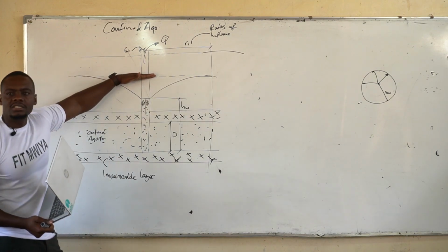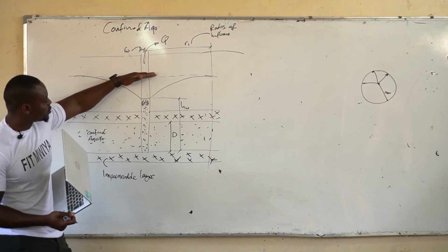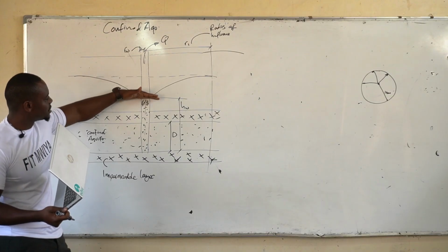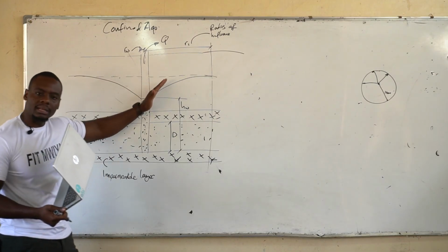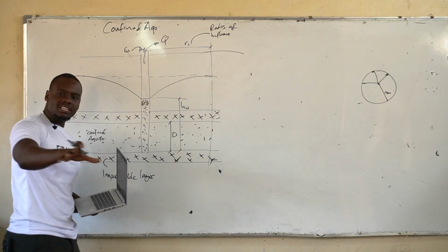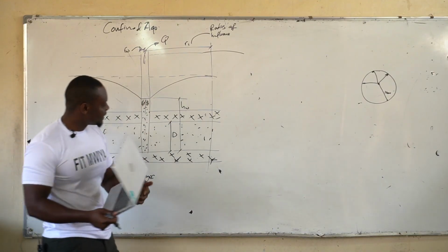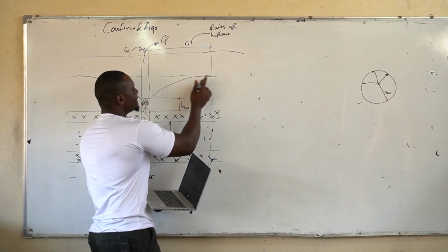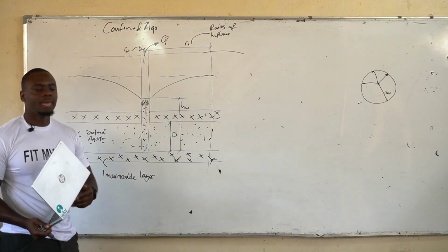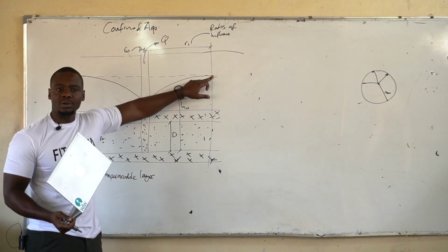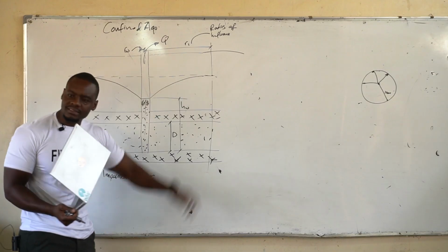So this one is just showing the original water table. And then, of course, with time and with pumping, the water table just sort of drops. And if it is dropping, it is dragging along that line. And the radius of influence is always from the centroid of your borehole to where your curving just starts to touch the water table. So where the water table is still original, that's how far your borehole is affecting people. Does that make sense?